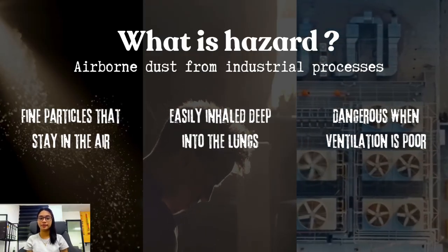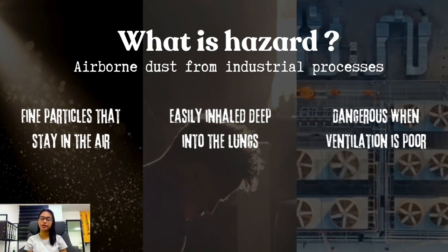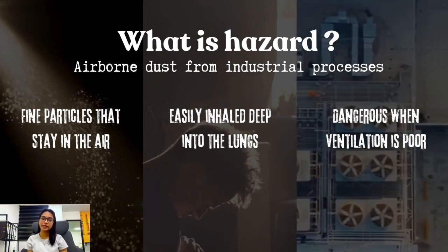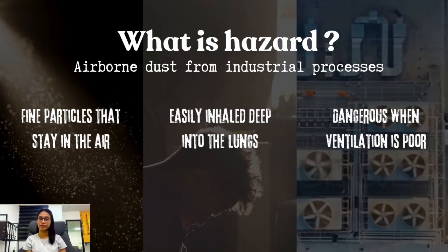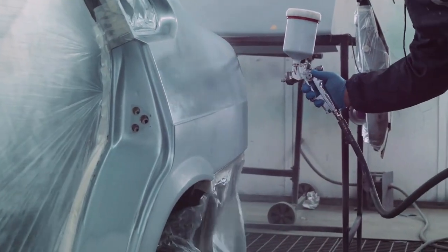So what is the hazard? Dust becomes a hazard when tiny airborne particles remain in the air due to poor ventilation or lack of control measures. These particles travel deep into the respiratory system and can cause short-term irritation and also long-term illness. Activities like cutting stone, concrete or wood with power tools, working with flour, welding and chemical spraying can release harmful agents. These are often invisible to the naked eye.